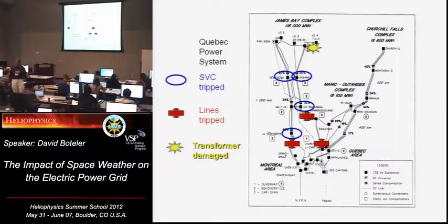But a whole area that we haven't looked at that needs to be looked at is the inductance of the power system. And of course, you've got these enormous transformers there, so they've got significant inductance. For this, we've been just modeling it as a resistive network. So I'm thinking before we rush off to do a lot with faster sample data and look at higher frequency events, we need to look at what the actual response of the power system is. Because I think the power system is going to damp out the higher frequencies.